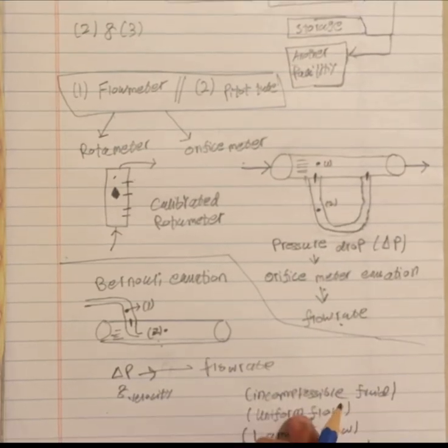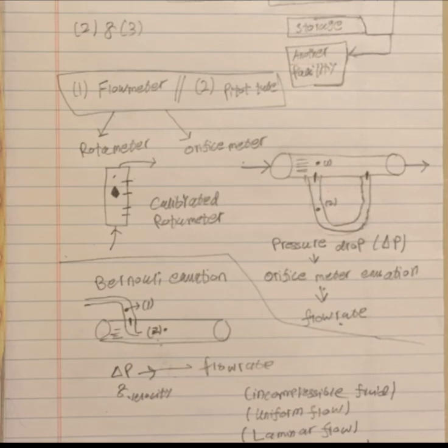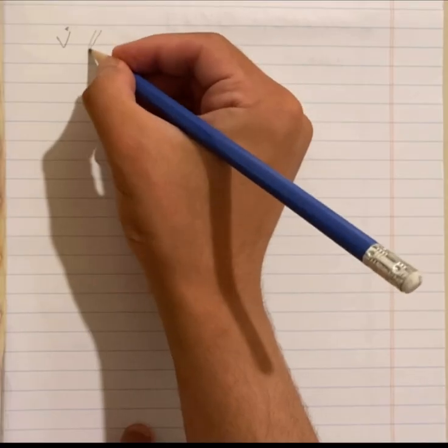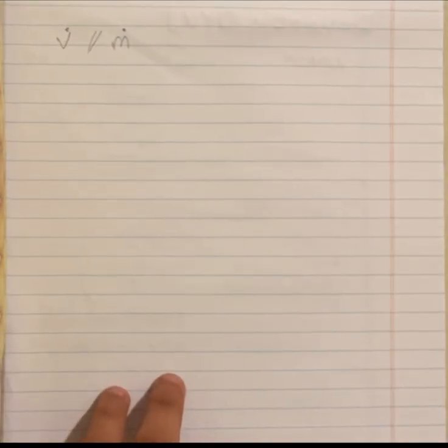It also fits. I've said measuring flow rate so far, but I didn't specify which flow rate. Whenever you want to measure the flow rate, you either measure volumetric flow rate or mass flow rate. They are the easiest flow rates to be found, especially volume flow rate. In case of rotameter, just read from the float, and with a stopwatch you can find the volume flow rate easily. With mass, you may do a little bit of hard work, but it's not that hard compared to other flow rates. So you will either face volumetric flow rate or mass flow rate. Especially in laboratories, the most common one that you will calculate is the volumetric flow rate.